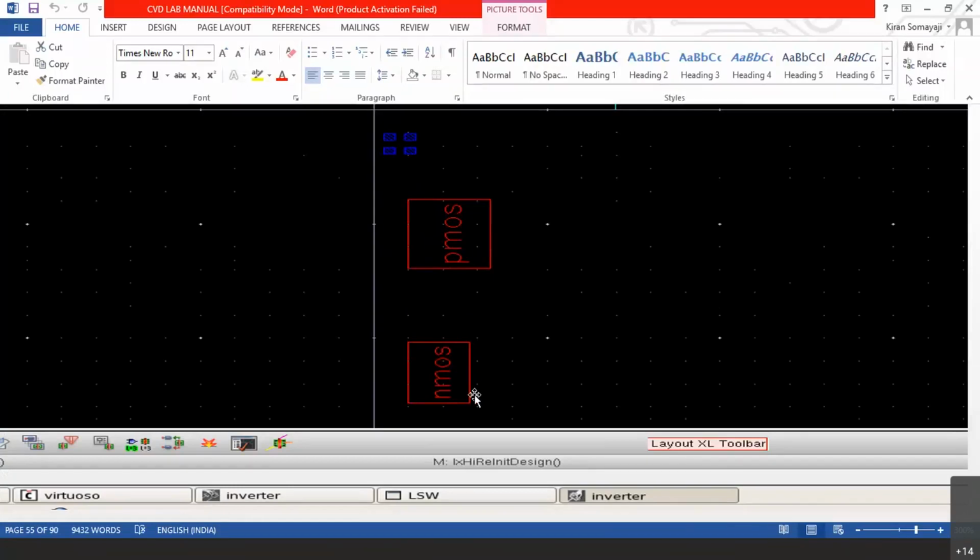If you want, you can make a layout of the device on your own also. That is called completely full custom design. That is also possible, but here it is not required for us. Why? Because we are already using a 180 nanometer technology and we have already specified the device dimensions in terms of width and length. So by default, it is going to generate that layout.